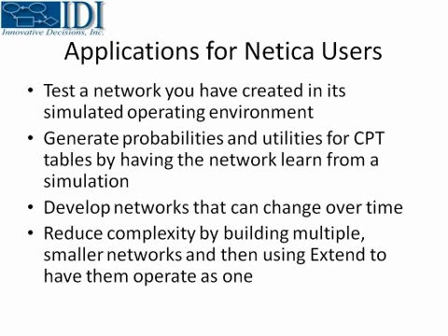If you're building a diagnostic network on an engine, you can build one network on the fuel system and maybe another network on the cooling system and another on the oil system, and then have an overall network that looks at the health of the engine from all of these sub-networks, as separate networks as opposed to trying to make one gigantic network.